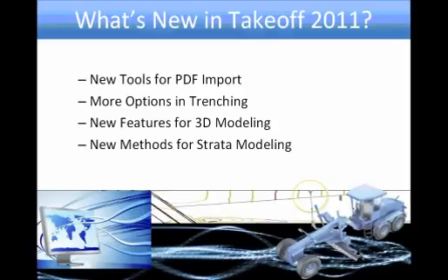So, what's new in Carlson Takeoff 2011? We have new tools for PDF import. Last year, for 2010, was the first time we were able to bring in PDF. We now have new commands that will allow you to be up and running with that PDF a lot faster in terms of scaling it and also putting line work to different layers and getting clean line work from that PDF.